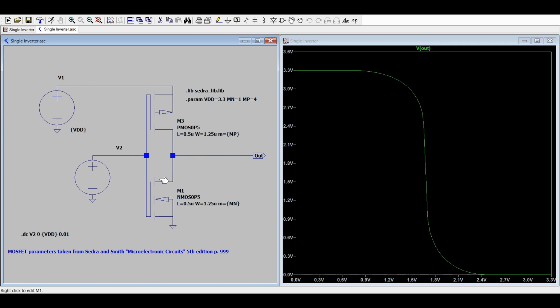If I were to put in a very high-speed sinusoid into this, I would get out quite an interesting response because these FETs have got capacitances, etc. But we will worry about that another day. In terms of the steady state response, we see that there's this very nice sharp transition here. And later we will learn that this really helps increase our robustness to noise.